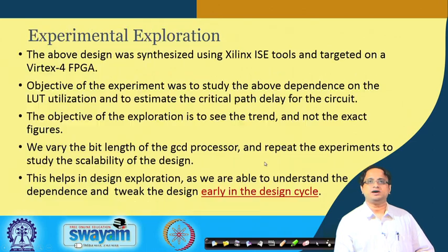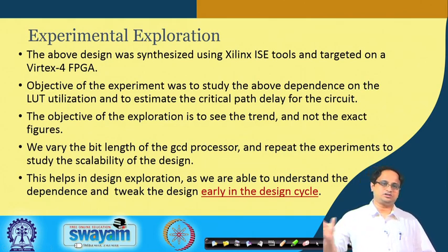With these estimates, you can try to experimentally validate. The idea is that you can take a Virtex 4 device and a Xilinx ISE tool, or any other FPGA tool, and repeat this experiment for different versions of GCD. You can do GCD implementations for different bit lengths and see how your design scales. You will get some estimates from the CAD tool, and you can use these modeling estimates also and see how well they correlate.